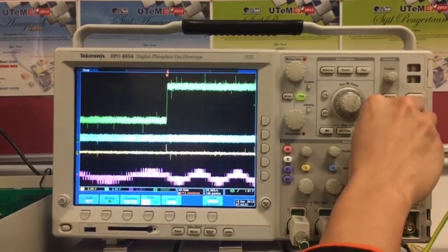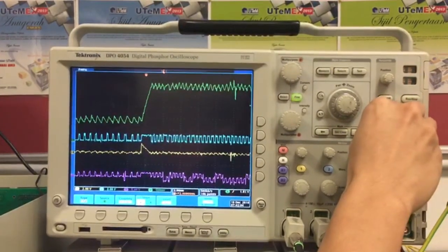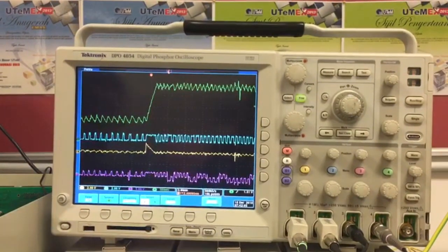After zooming in on the result, we notice a change in the error torque signal during the rising interval of the output torque. The third line on the oscilloscope, the error torque signal, overshoots shortly before falling to its nominal value. It results in a larger duty cycle or switching signal for the induction motor. At higher output torque, the width of the duty cycle and D-frame voltage signal controlling the induction motor has increased. It is done to maintain the output torque of the induction motor.